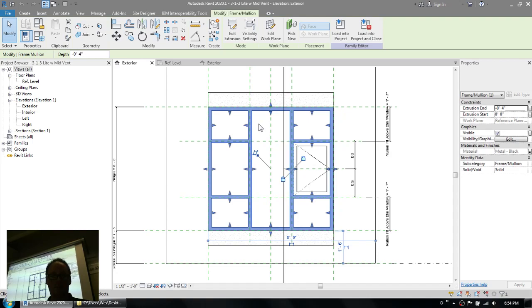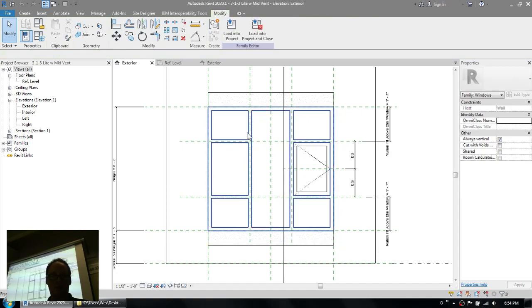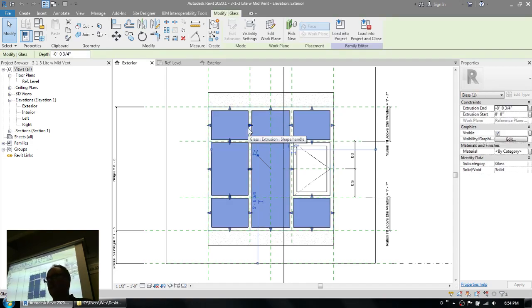Next, after the window frame's been built, if you put your cursor on the edge of the frame and hit the tab key once, that is the glass in the window. So the glass, it's fixed glass. It's not part of a vent in the window. So that's the second screenshot in the first page of the Session 6 notes.